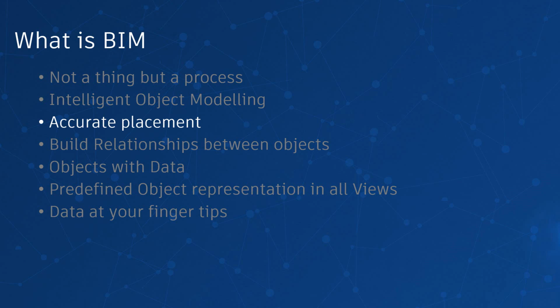And with BIM, the difference is that you're placing things accurately in more of an intelligent space, giving you a 100% real representation of what it actually will look like, or close to 100%. In some cases, we actually build relationships between objects. So, for example, locating columns on a grid line, so that if the grid line moves, maybe we get the column to move, or relationships between, say, a steel beam and a steel column, for example, right?